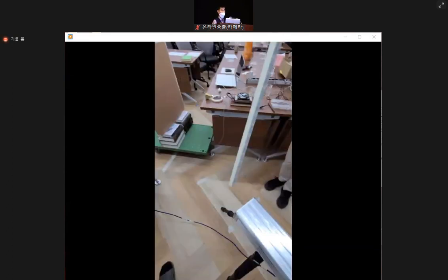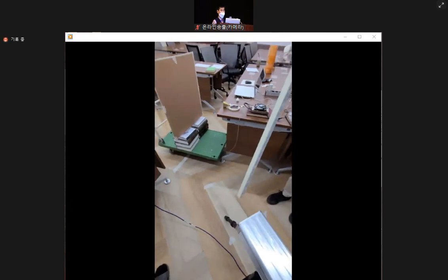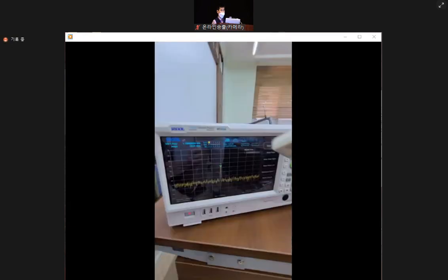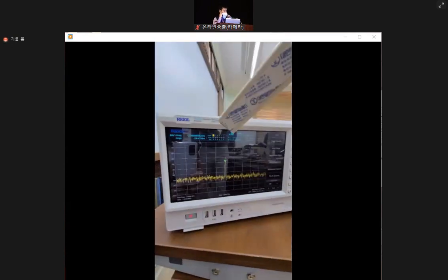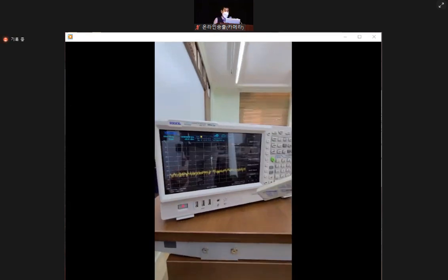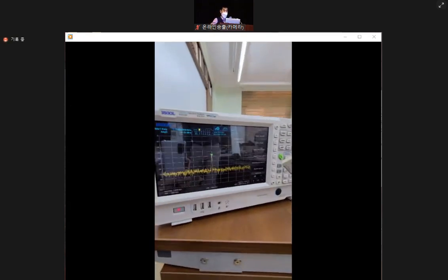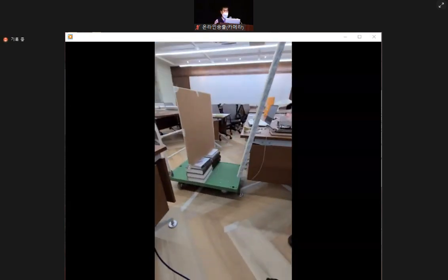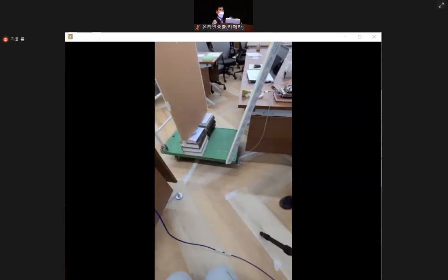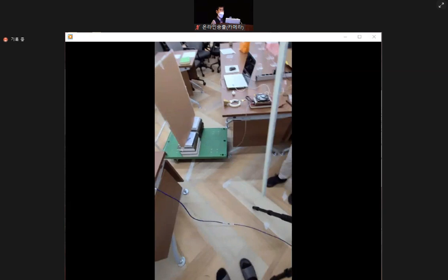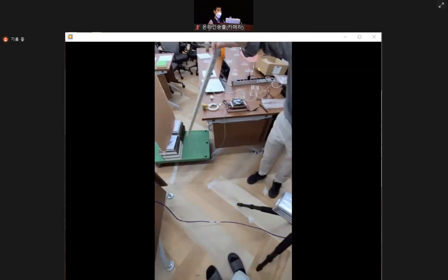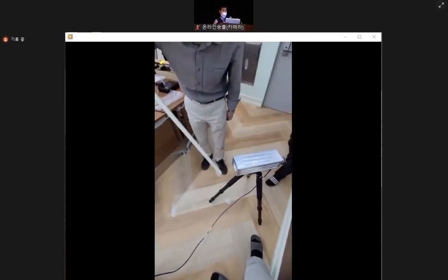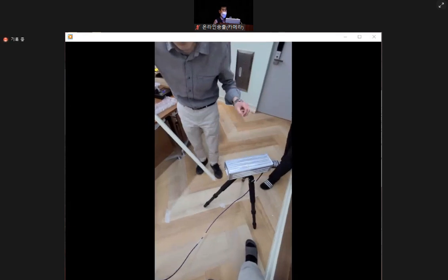Let us confirm this by changing and checking the strength of the received power. Here we will read the strength. This spectrum analyzer is attached through the cable to the probe. Some dBm. You can see the green marker there that tells you the strength. The signal strength has been lower than before. Why? At the same angular position, but the distance has increased. So it is no wonder we can see the weakening of the received power.